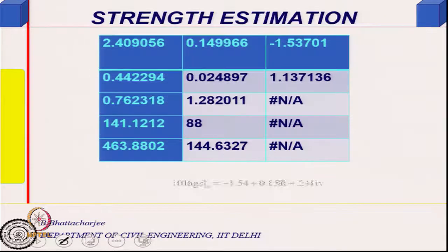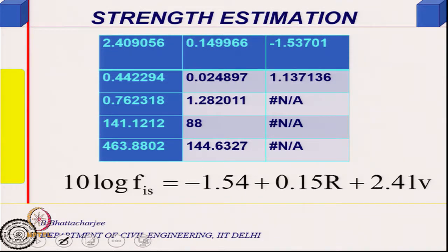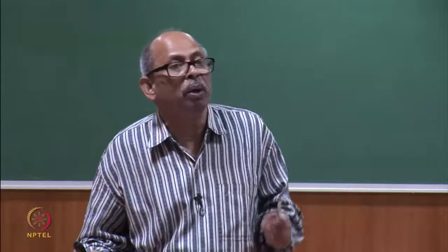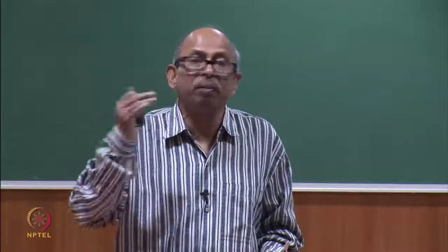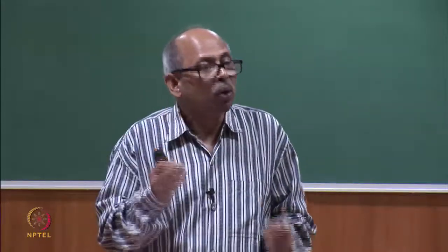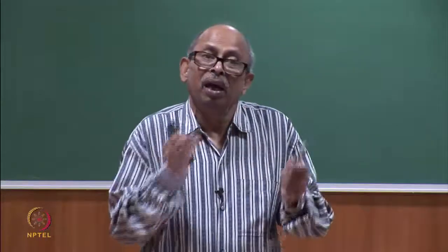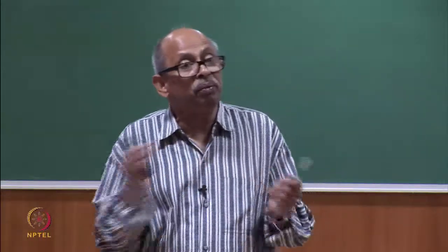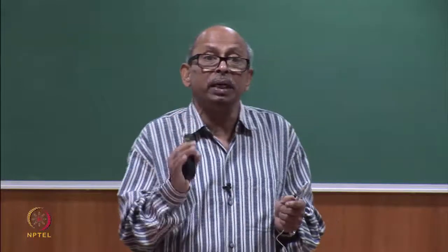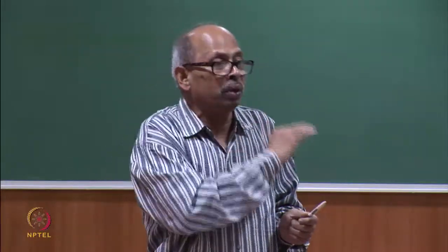Finally, we established a better correlation, and this line seems to be fitting better. Then we predicted strength in many places where we had only taken rebound number and ultrasound, which was 350 or something of that order. Cores were much fewer, so we could now get full information about the strength, which columns needed strengthening and which did not.